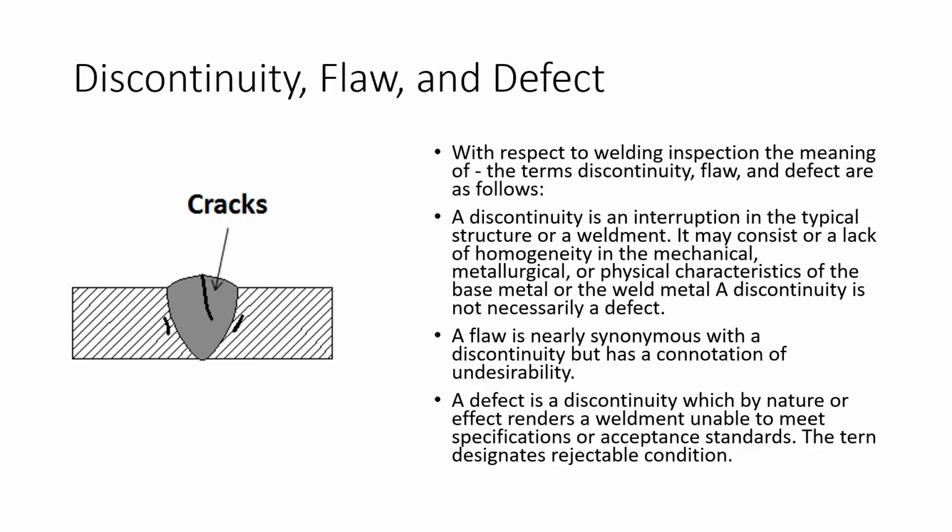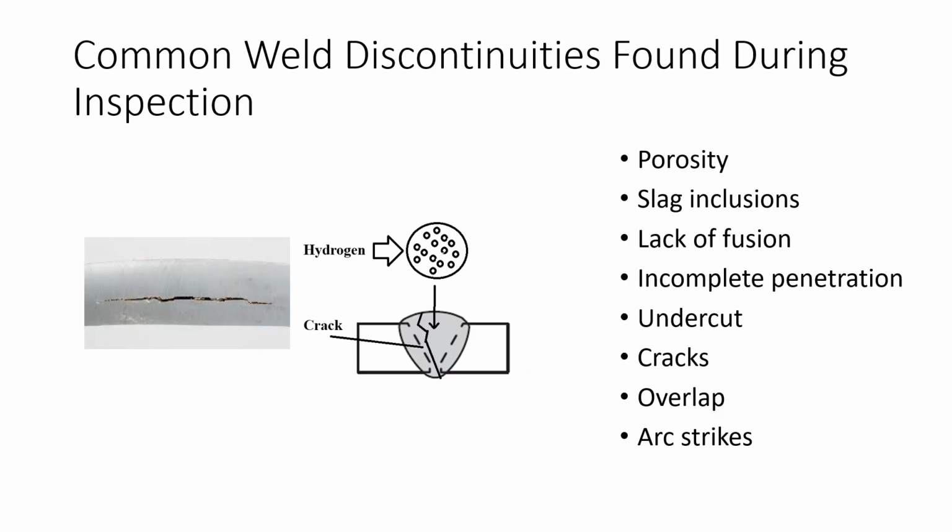So here's a list of things that we could reasonably expect to find if we're doing non-destructive testing on welds in this case. We've got the laundry list: porosity, slag inclusions, maybe tungsten inclusions, undercut, cracks, all of this stuff. We can find these things with our various toolkit of non-destructive testing methods. And that's why we use non-destructive testing: we can go in and find things and not have to rip something apart. And we can do it relatively cheaply.